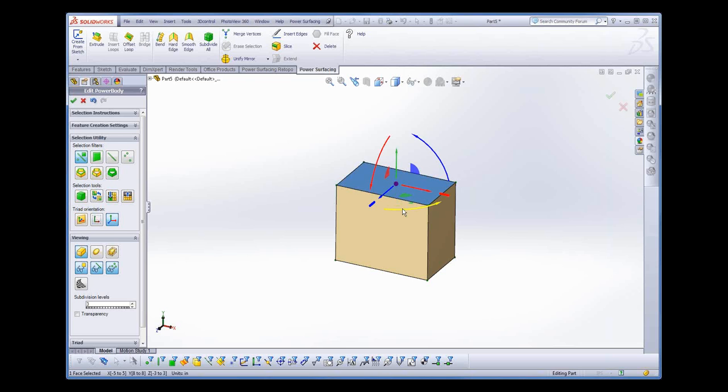And one of the differences with this is that we're actually transforming, move, rotate, scale, different sub-objects. Right now I've got a face selected. I'll now select a vertex, and there's an edge. And we can affect these things directly. First thing I want to do with this guy is scale in the top of my gas can. And notice that our triad has a lot of controls on it. We can do a uniform scale from the center. We can do a non-uniform scale, which is what I'm going to do. And we can also constrain in the Cartesian directions here. So I've got my scale done.